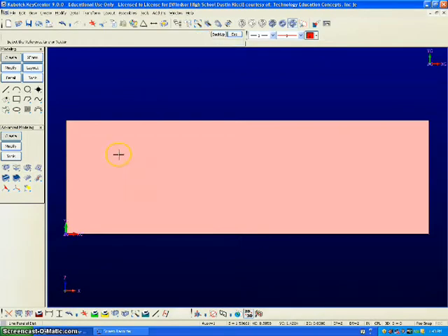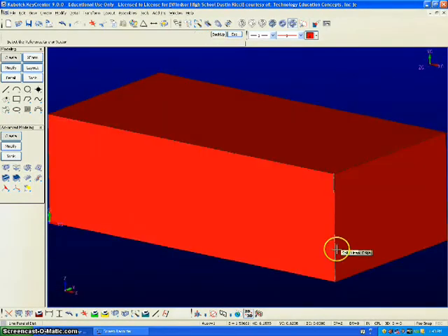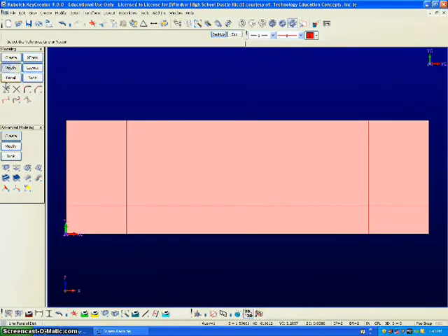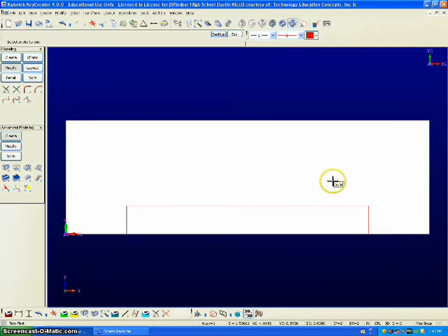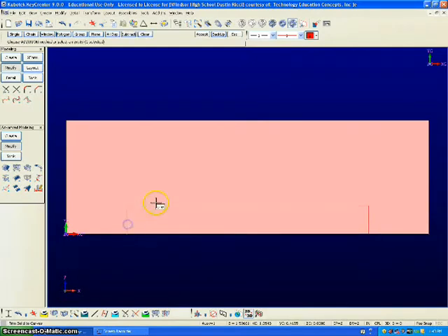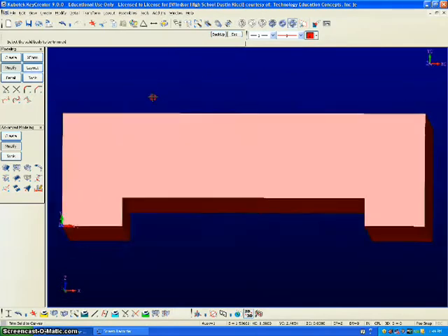Let's go 1, enter, and from the left and right sides, and 0.5 from the bottom. So that's done. Now modify, trim first. This rectangle will serve as what we're going to cut out of our main block. Modify advanced trim solid curves, OK, and select the 3 lines that we just trimmed. Accept, select the solid body, and click on the arrow pointing to your left. And that part of our block is now gone.